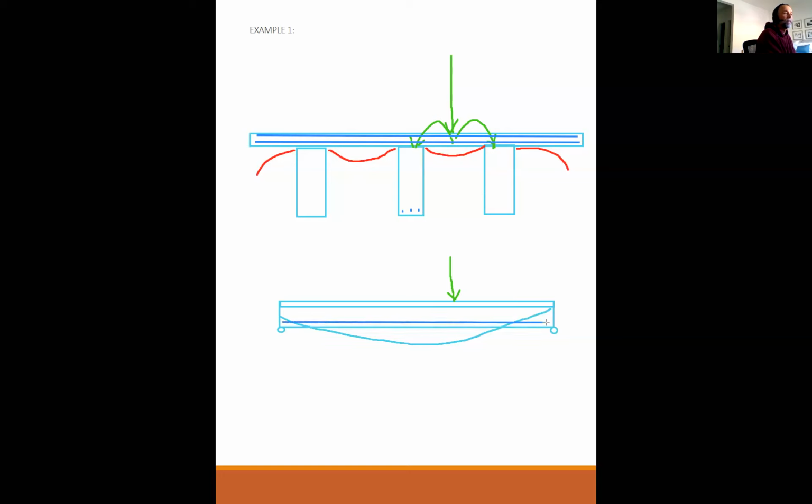So it's down here, spanning in and out of the page. And then if I look at the slab reinforcement, those now are dots because I'm looking at it from the side. See, so the whole system is 90 degrees to each other. The slab is just distributing the load to the beams, and then once it gets into the beams, it turns 90 degrees and heads off to the ends of the beams.